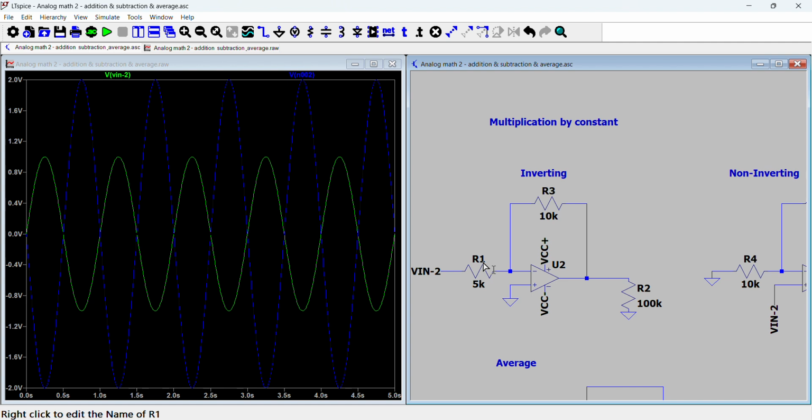So in the case that we want to supply a very high output impedance signal, for example from a very low voltage sensor, a very low current sensor, this inverting config is going to become problematic. So we have to make this resistor really, really large, and therefore this resistor has to also be large in order to overcome the output impedance of the input signal.